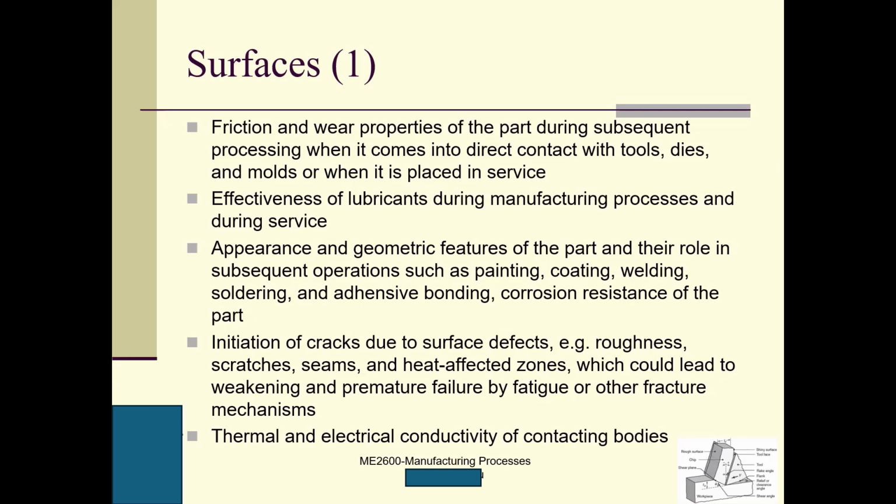There are a lot of different coolants. We have fluid coolant, mist coolant, also minimum quantity lubrication, and we might even use liquid, what do we call it? Liquid oxygen, right? We put liquid oxygen there to cool it. By the way, titanium is very difficult to machine. I had the experience when I machined titanium. The titanium caught fire. It burned. Okay, so this is because of heat.